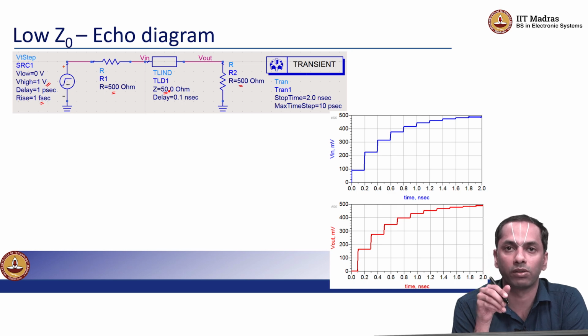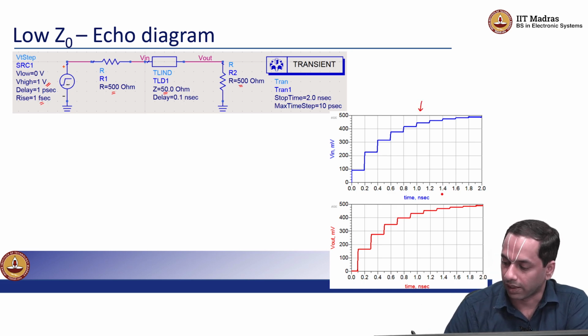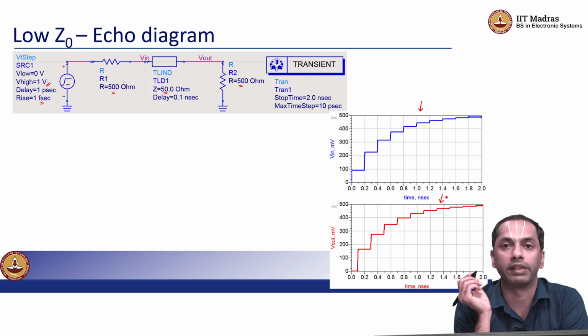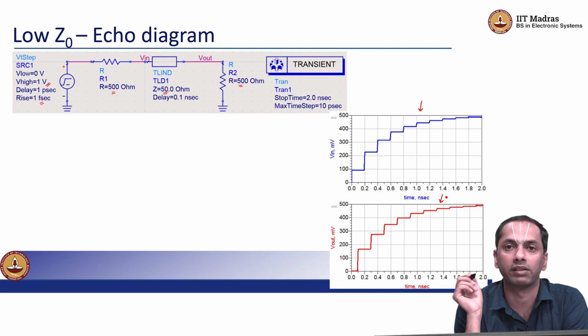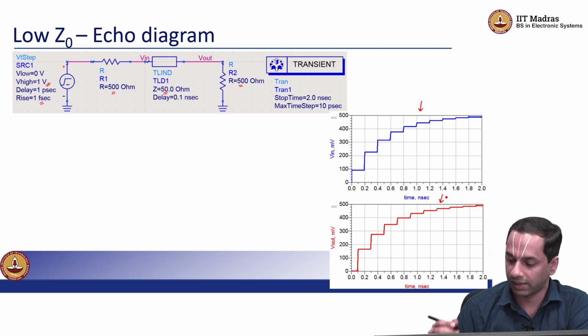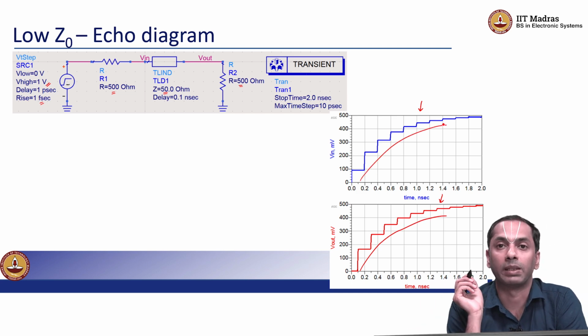If I do a simple transient simulation with the transmission line effects, I basically get the kind of figures that we got step by step by evaluating the reflection coefficients. A computer is able to generate this quite quickly for us, but nevertheless we are seeing the same shape. Remember, we are after an intuition for these shapes.